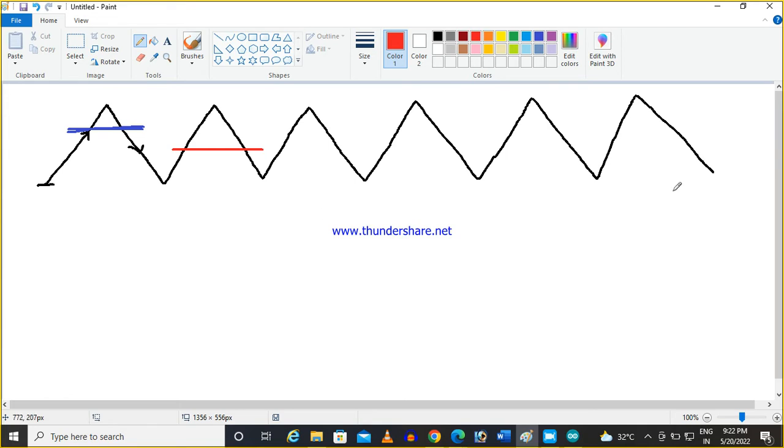If I define 1, that means set while up counting and clear while down counting. While it is counting up and there is a match here, the pin goes high and maintains that state, and while down counting, when it matches, it clears.